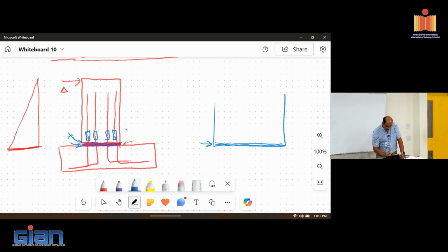Very unlikely you will see any crack developed in that region, because of what we discussed. You have a chunk of steel sitting there, and the reason you're developing a crack is that you establish certain strain, and that strain is transferred to the reinforcing steel.